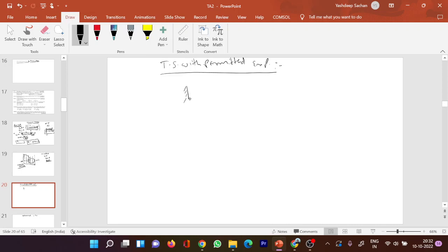So here what would be the case? This is the L, and here some expansion is permitted, and let's suppose this is the delta. Now here we have to increase temperature only, right? A decrement in temperature is nothing, because if you decrease, then it will simply go back. No issue. If you increase the temperature, then only stress will come, right?